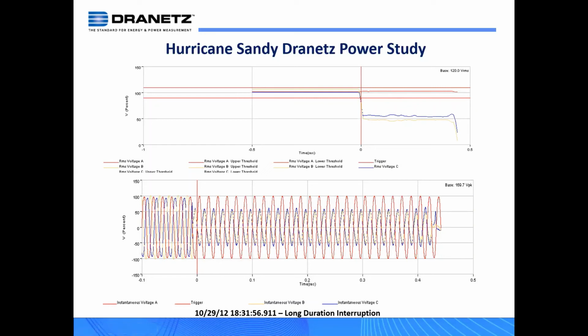So think of your facility, if maybe your lights and other systems are powered from B and C, and you think that they're off, but you have other devices that were powered by A and they're still energized. If you didn't take proper precautions and you thought you had power disengaged and someone touched that without wearing gloves or turned off the breakers or the protection, there could be a safety issue that was introduced as a result of this.